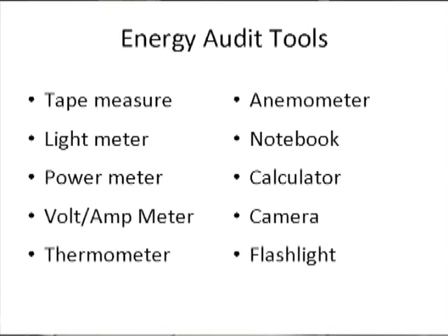Thermometer, anybody can operate. An anemometer shows us how much airflow, what the speed of the airflow is. It kind of helps us diagnose some of the airflow issues in the building on the air side. A notebook's key to keep notes as you go around. My favorite tool is a camera to be able to take pictures of everything, and I write down the picture number next to my note, and then I can build a report when I get back to the office real easily.